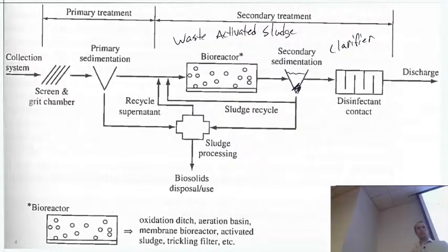It removes almost everything, and we disinfect to catch any of the remaining. We don't need it to be quite as pure as drinking water for obvious reasons, so we don't hold it to the same exact standard, but we will usually disinfect and then discharge. Depending on what kind of water is receiving, we might need to remove the chlorine. In some cases, it's not really necessary. Depending on how the mixing zone occurs, is the chlorine going to be some threat to the environment? Of course, we don't always have to use chlorine either.